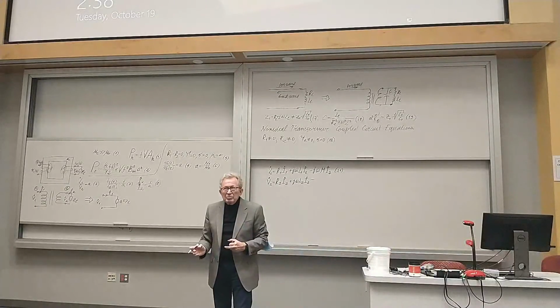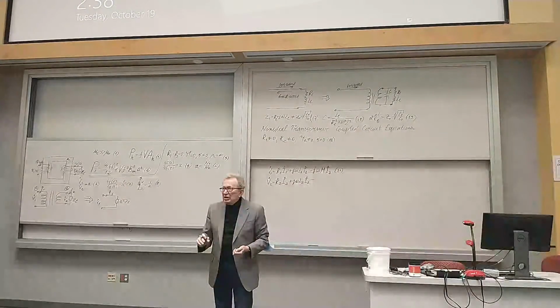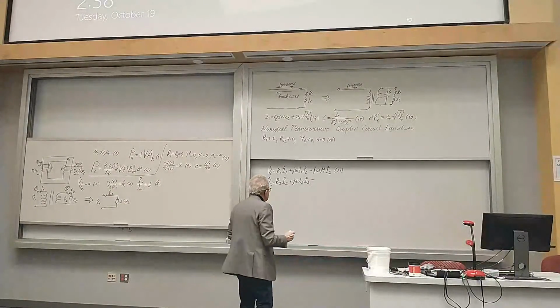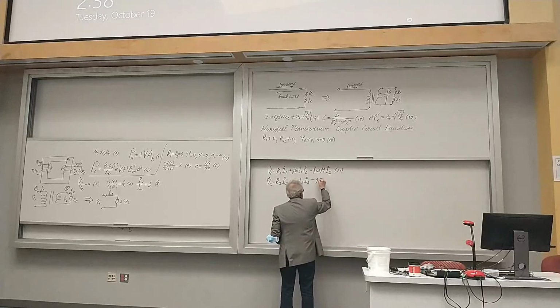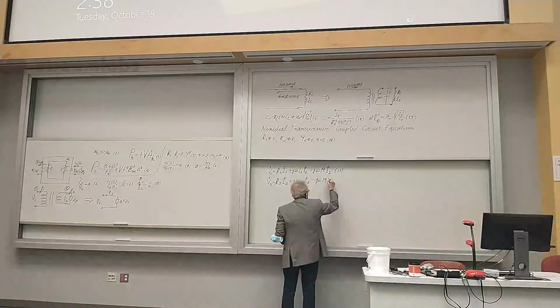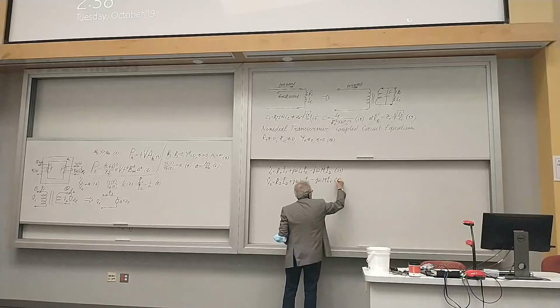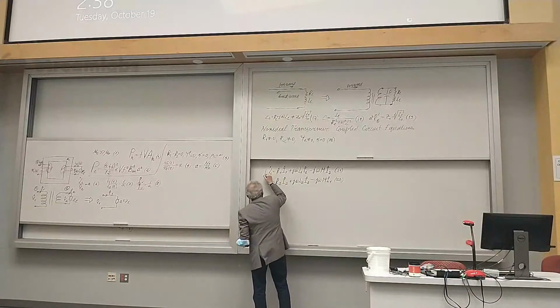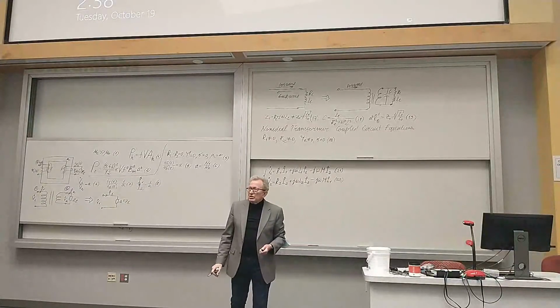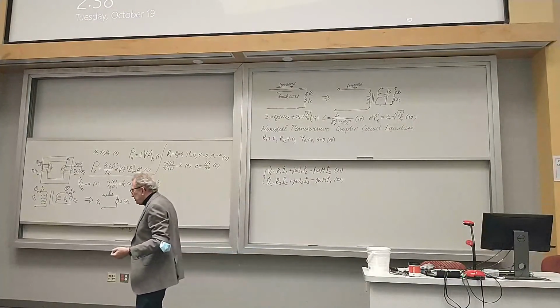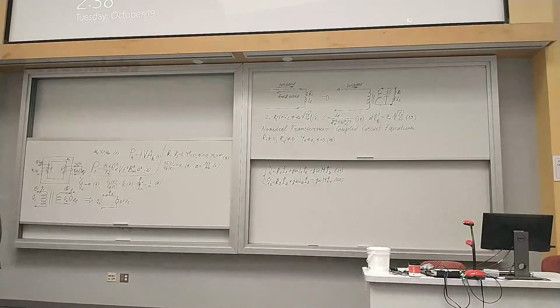There is a current through the primary winding. It creates a magnetic field, represented by the magnetic field lines, which link the secondary winding, and because it's time varying, they will induce the voltage. So here is a coupled circuit equation. The two are mathematically coupled because there are two variables in each equation. Physically they're coupled because of strong electromagnetic coupling between the primary and secondary winding.